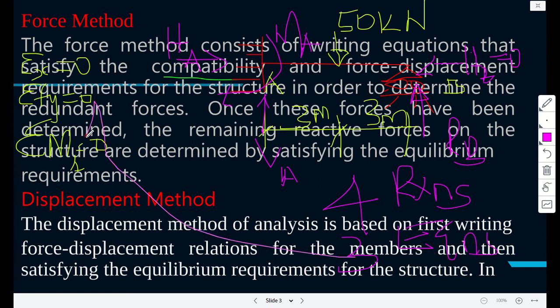The three equations we are talking about are these ones. The reactions are this, that, and the moment, and RB. HB is already known, so you cannot count it. We know it's zero because, by definition, for a roller support, the horizontal force is zero. So to solve this, you will need to reduce this structure to a statically determinate one, which you can solve.